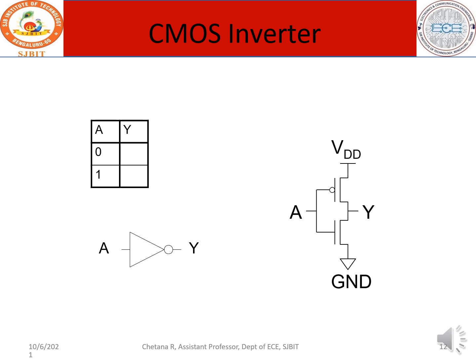And this is the CMOS device, the CMOS inverter. Please notice here, you have this as your NMOS, no bubble, and this is your PMOS. So this is your N-type device, and on the top you have your PMOS device. Why is it PMOS? Because there is a bubble here.